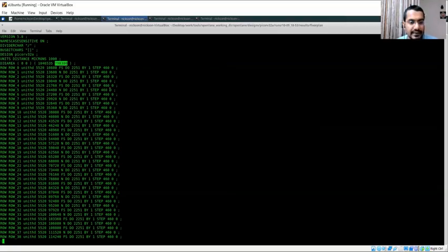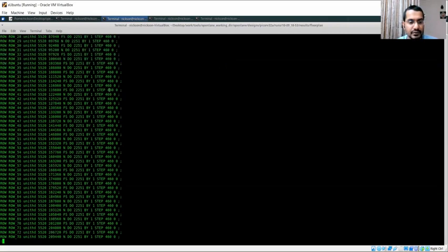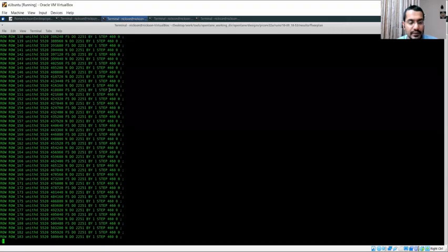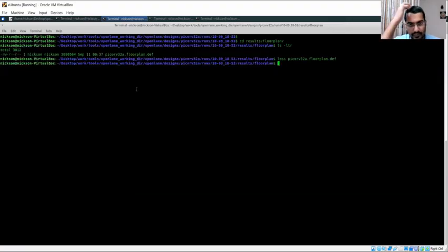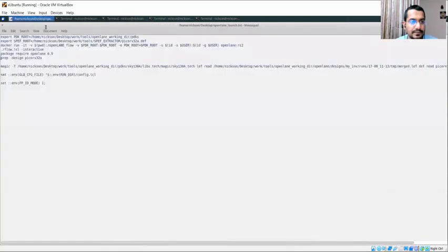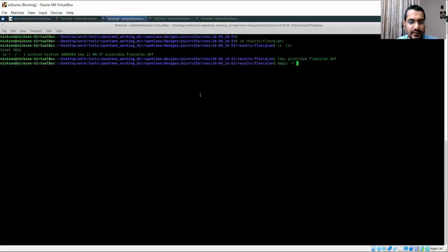So this is the def file, but looking at the def file does not make any sense. You won't know where what is placed. So to see the actual layout after floor plan, it is first done in Magic. So you do magic -T for tech file. So tech file location I have here. This is the complete tech file location.